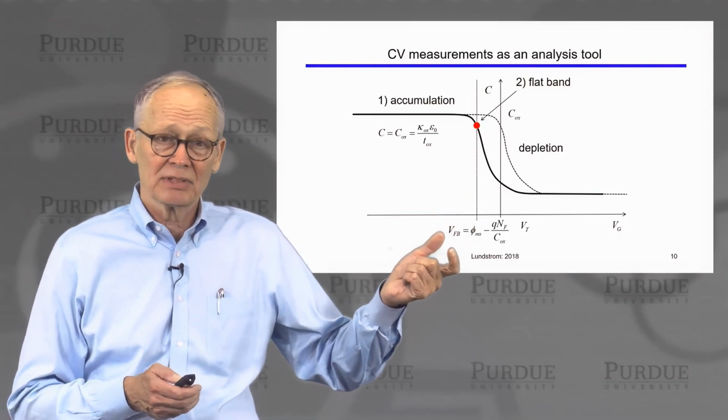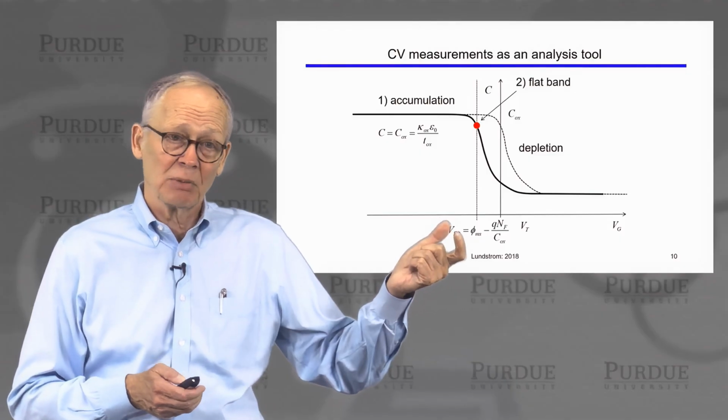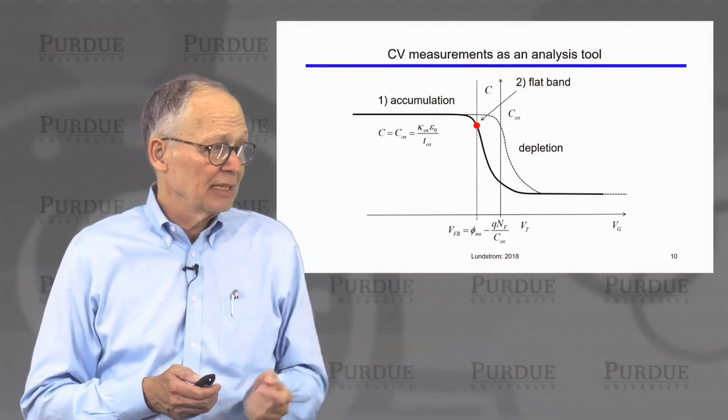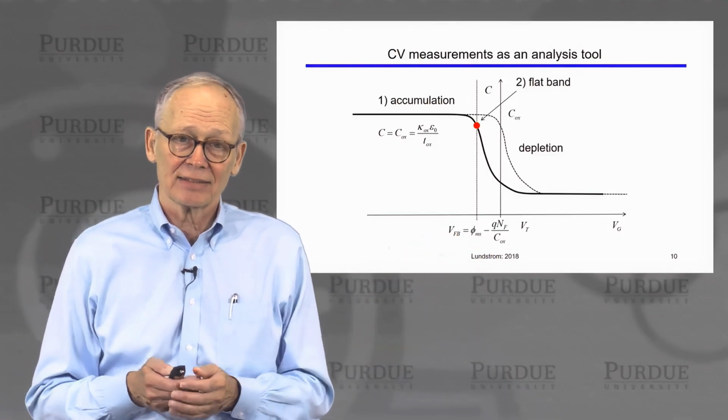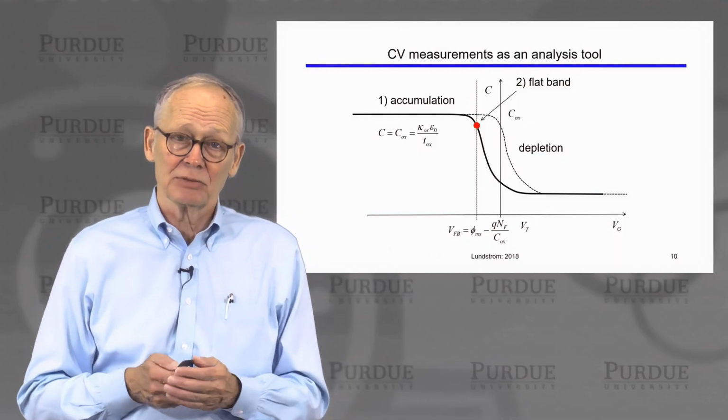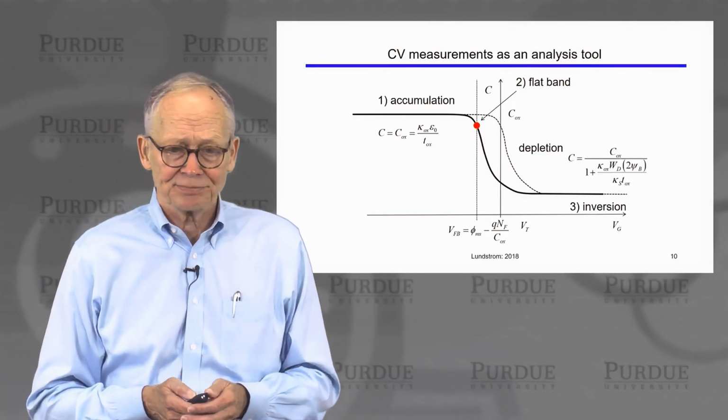If you know the metal semiconductor work function difference, and you probably do, then you could deduce how much charge there is at the oxide silicon interface. So that would be a useful thing to be able to deduce.